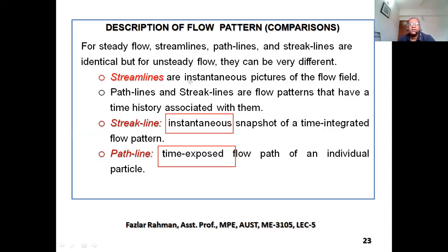Streamlines are an instantaneous picture of the flow field. That means based on the time. What is the definition of the streamline? At every point you make a tangent, and that tangent will give you the direction of the fluid particle.